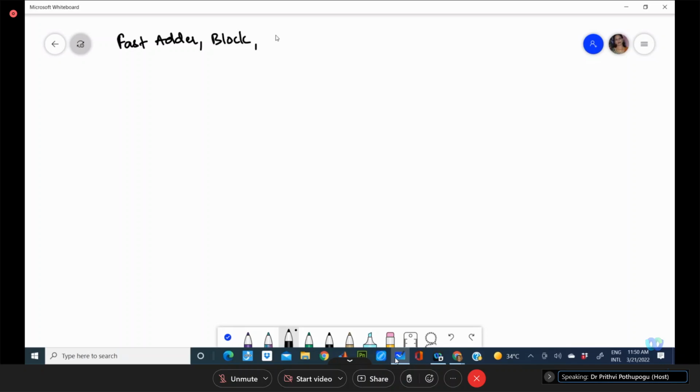Repeatedly you do the subtraction, that becomes a division. That is a theoretical way of explaining how your adder or subtractor can be used for implementing a multiplication or division process. But actually, when you take the concept of adder and subtractor, we never take the subtractor as a separate design, but we use a complement addition aspect to implement a subtraction.